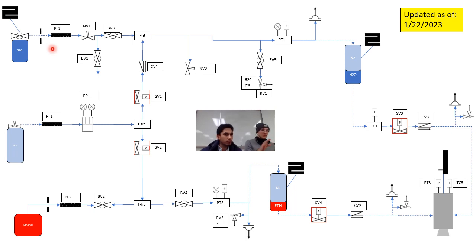And you're going to have to pressurize the nitrous oxide bottle with nitrogen from maybe another tank, ideally from another tank, I would say. Pressurize that back to 900 or back to whatever the maximum safe amount is, and then you could put it back on. Because you're pressurizing it with the gas, that gas will stay on top. It'll push down on the nitrous oxide, and you'll get the same benefit of pushing 900 psi into 820, 850, whatever it is, as you did before. So that process needs to be experimented with to figure out how easy it'll be.